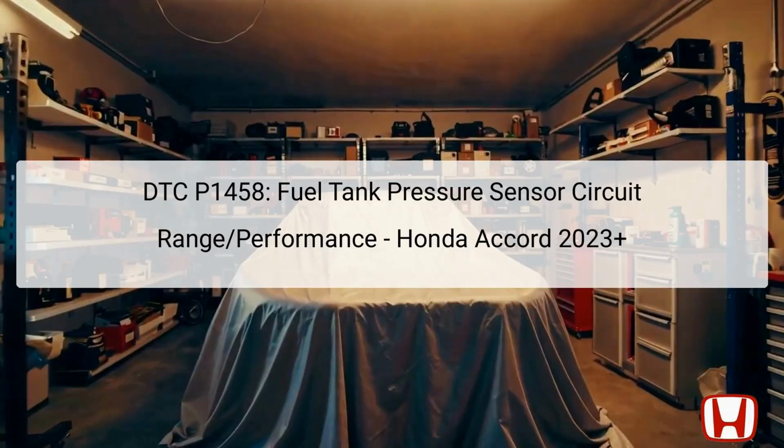Welcome to the diagnostic presentation for DTC P1458, which stands for Fuel Tank Pressure Sensor Circuit Range and Performance. This error indicates a problem within the fuel tank pressure sensor circuit. The specific role of the fuel tank pressure, FTP sensor, is to monitor the pressure within the fuel tank.